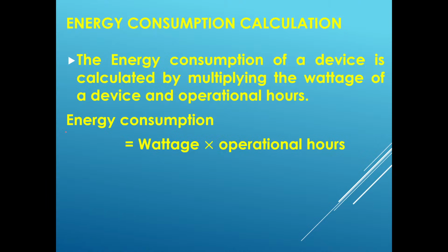What is energy consumption? Electrical energy consumption is wattage into operational hours, that is, for how many hours per day you are operating. So the energy consumption formula is wattage into operational hours. If you want, you can note this down. I will wait for a few seconds.